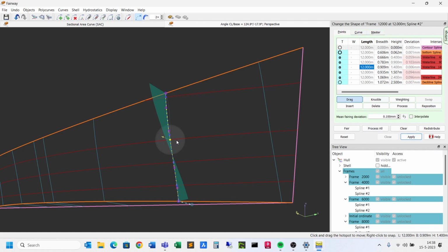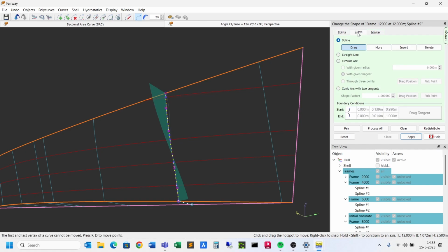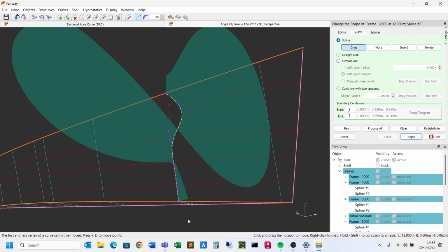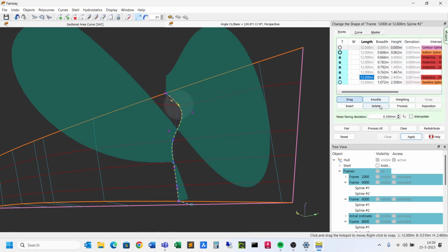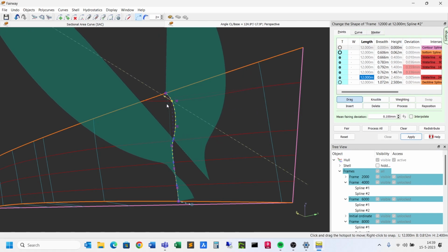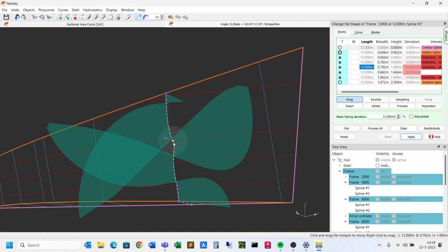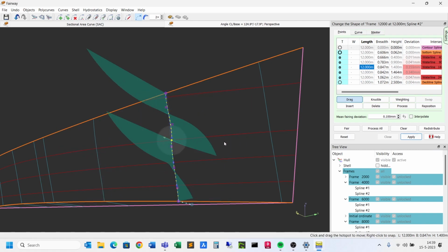Yeah, sorry, I haven't used Fairway before, but when you talk about vertices, I understand that these are connection points with the water lines. No, these are the vertices. Okay. So it's a NURBS curve. Yeah, it's vertices for a NURBS curve, basically the attraction points for the curves, if you like. And we can play with them, but they will be overruled as soon as I drag this point in again. So they will be recalculated. They are not the most consistent part of this, because they will be recalculated basically with every action I do.